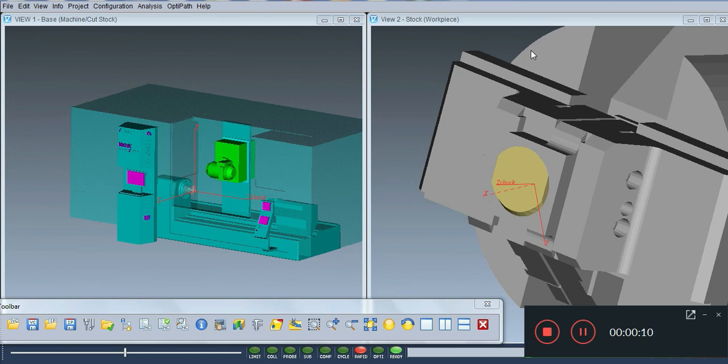A Milltown machine is a combination of milling and turning, which can be done in one. Depending on the machine type, it can let you do a 3+2 or a full 5-axis simultaneous. It depends on the control. If you have full 5-axis servos and controls, you can do full contouring. At a bare minimum, most of the common controls in the market on a Milltown will let you do 4+1.